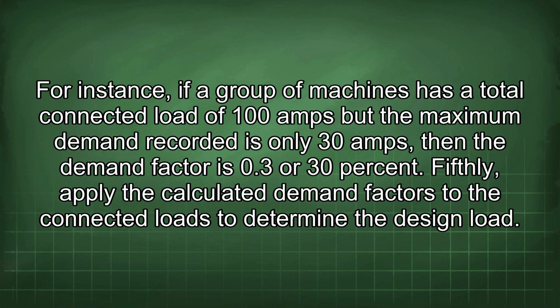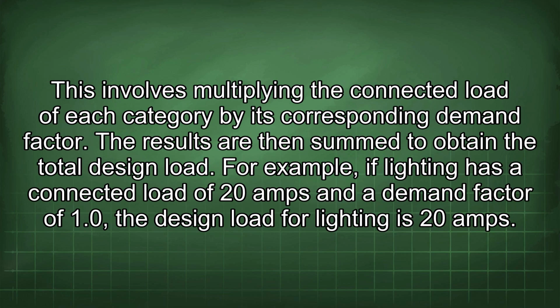Fifthly, apply the calculated demand factors to the connected loads to determine the design load. This involves multiplying the connected load of each category by its corresponding demand factor. The results are then summed to obtain the total design load.